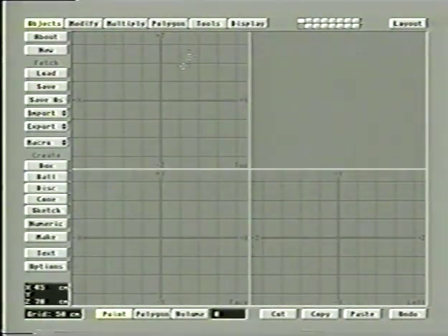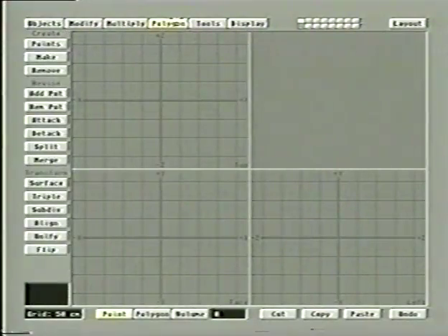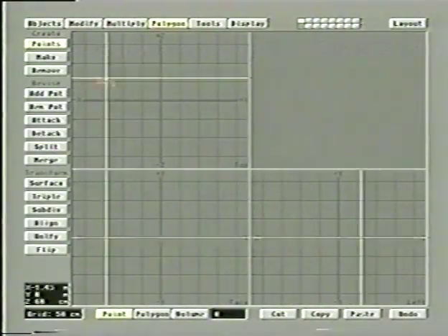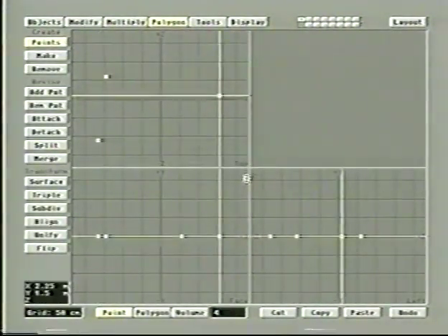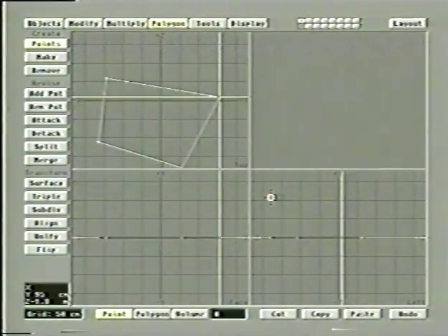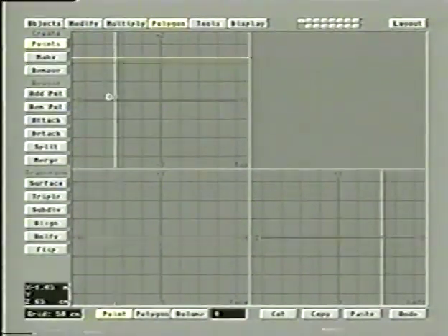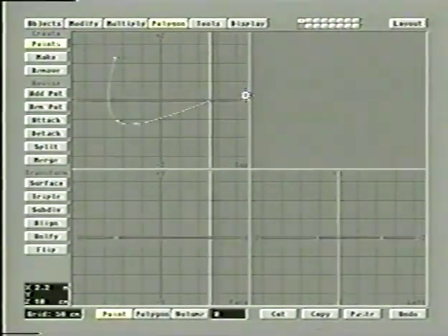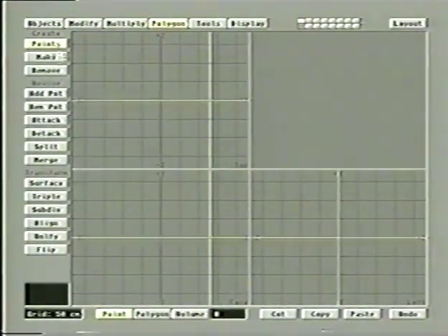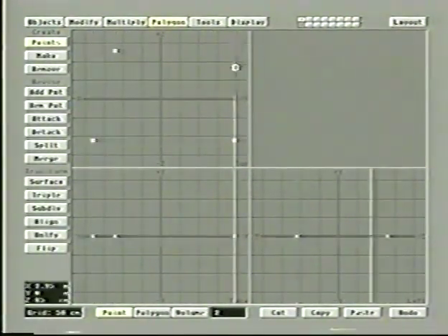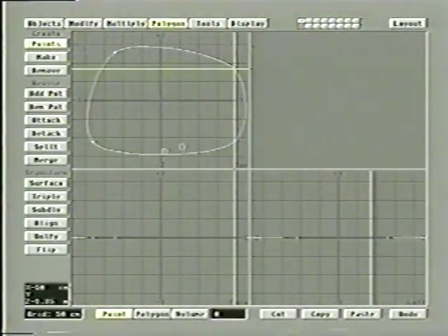And we showed you in tape 1 how you can create polygons or curves by just drawing out points and then connecting them using either the P function or the control P function that connects into an open curve, or control O, which makes them a closed curve. Well, there's another way of doing this without actually drawing the points initially, and that's by using the sketch function.